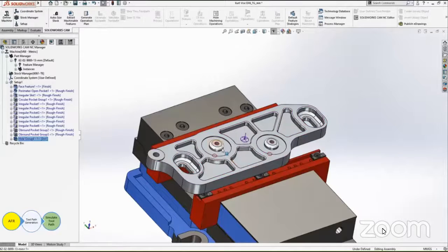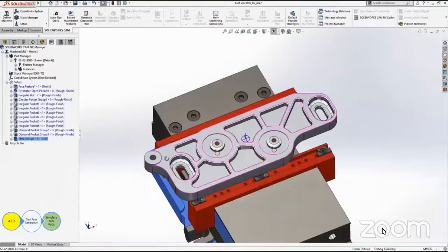This SolidWorks CAM AFR only extracted two holes, and it did not extract the third hole, which has a size a little bit different from these two holes. There can be various reasons why it did not extract the third hole. Either the settings were different. For that, no problem, we will create the manual operation on this third hole to create the center drill and the tapping.